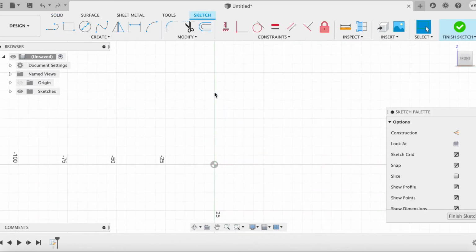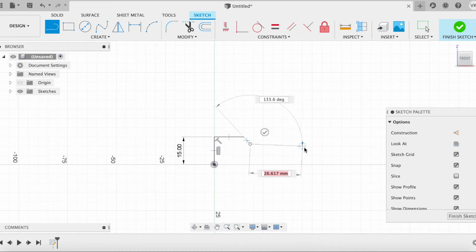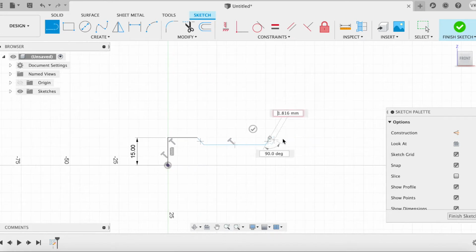Select Create Sketch, select a plane, and then start modeling the 2D profile to be revolved around an axis for your screwdriver handle. Go ahead, you can get creative in this area. We are sticking to a conventional shape for a better understanding.